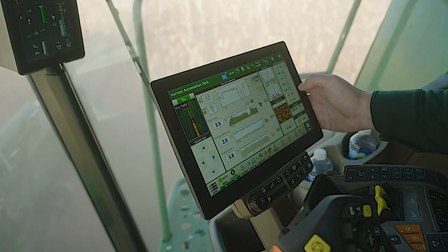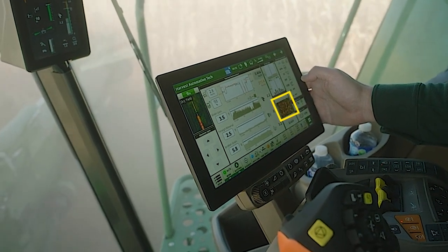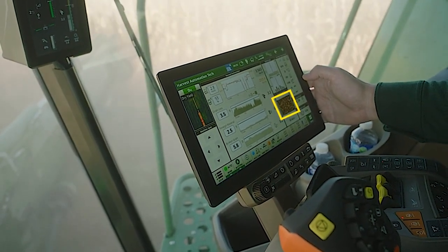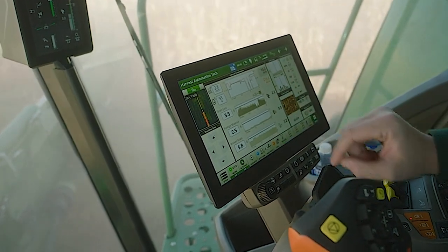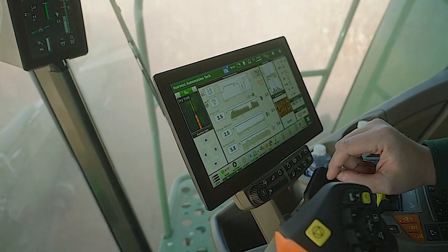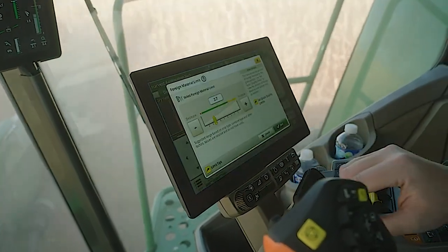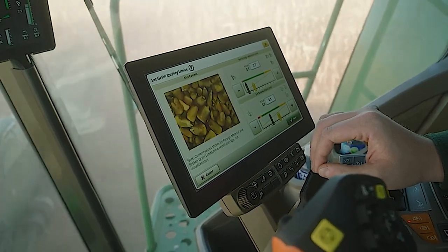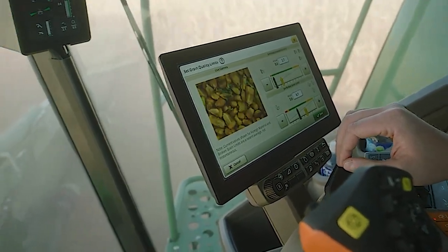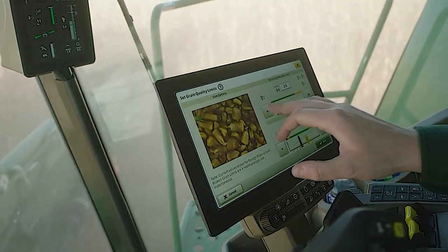To aid in guidance of the broken grain or foreign material limits adjustment box, recall we can visually inspect results by live viewing the camera feed and seeing how that sample relates to the current values the combine is running at or changes from adjustments. Similarly, the slider can be adjusted from this window for both foreign material and broken grain with recommendations. Sliding right permits more broken grain and/or trash in the tank.